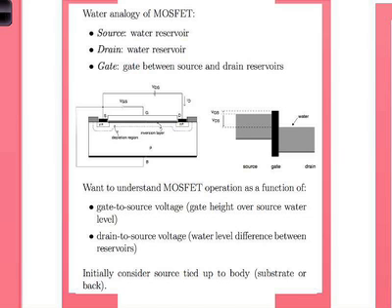So, the analogy is basically shown here. So, this is the MOSFET. Okay, so you have a gate, you have a source, you have a drain, and you have a region. Okay, we'll talk about what these are in a second. But keep in mind, typically, that the gate voltage is referred to the source. When you say drain voltage, it is typically referred to the source, and the substrate and the source are typically connected and grounded together. Okay, that's a typical situation.